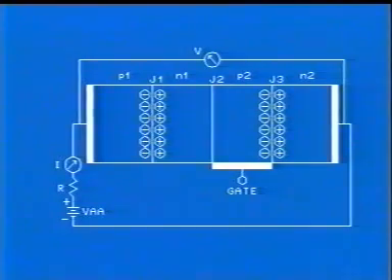Only body resistance and drop across J1 and J3 limits the current now. Drop across SCR is very small, of the order of 1 volt, and it remains almost constant. Hence, further increase in applied voltage leads to linear increase in current. Thus we see that the SCR behaves like a switch. When a voltage called breakover voltage is applied, it turns on.